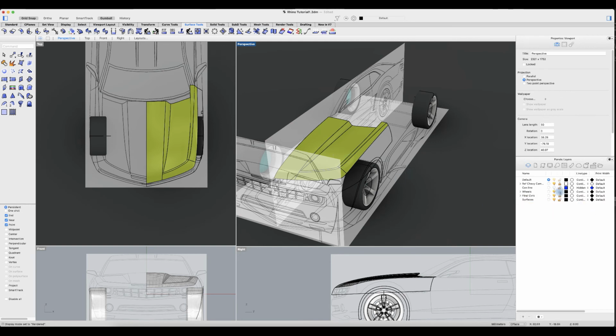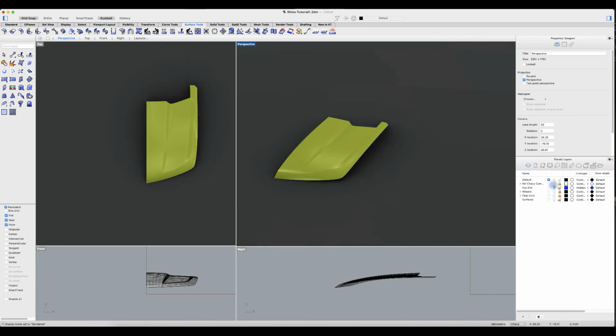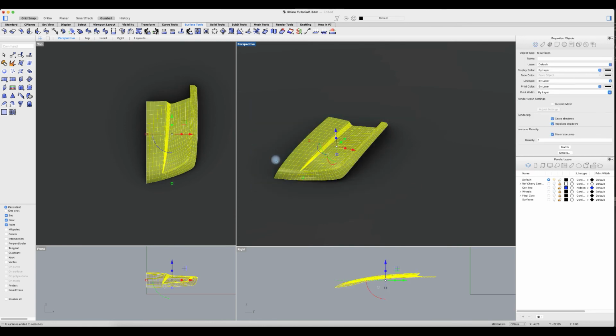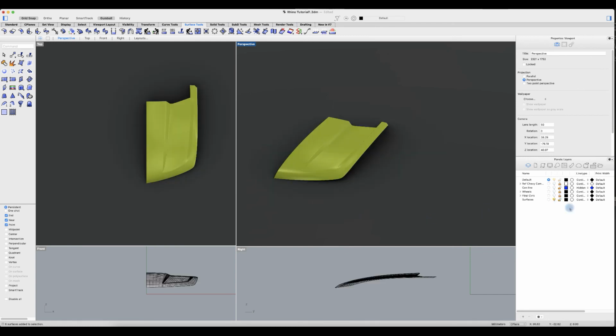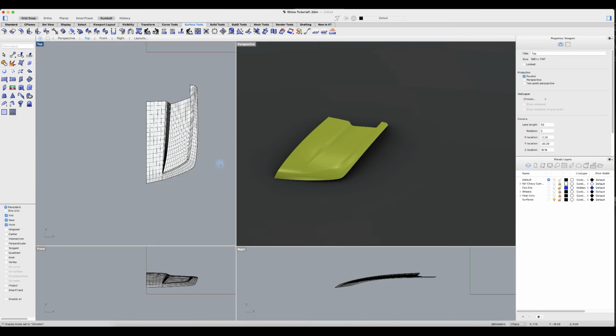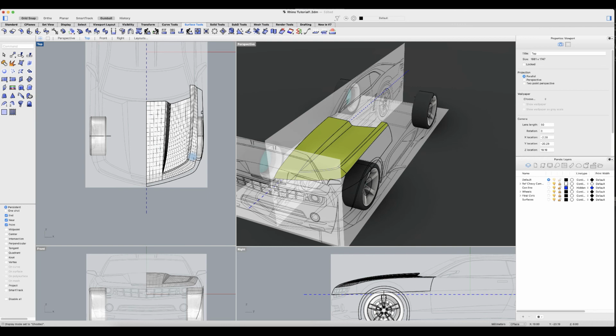And why don't we just select all this beauty right there and place it inside our surface. And let me use my ghost mode there. I'm going to turn on all my layers, and I am going to lock down everything except for my surface layer.